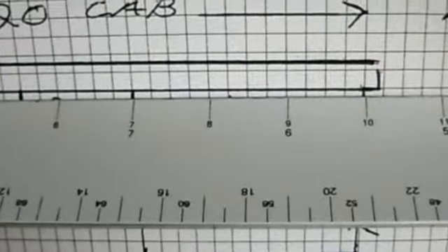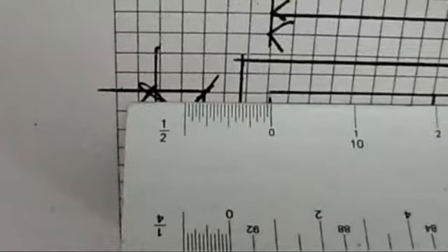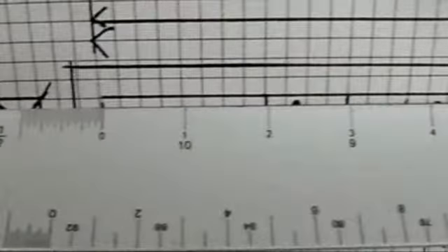So just to recap on measuring, all of our widths, all of our heights, windows, doorways, trims, mark it all down so that you've got it. Then on your paper, you'll draw walls. So what I do is I draw the interior of the room, 128 by the 122, and then draw approximately a 4-inch rectangle around that, which will represent your walls. So as you see, there's my walls. There's my 120 plus the extra 2 inches.